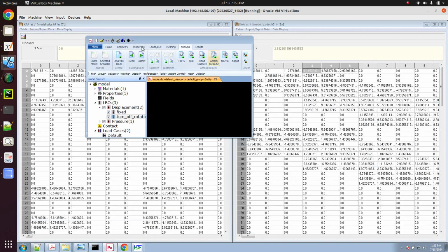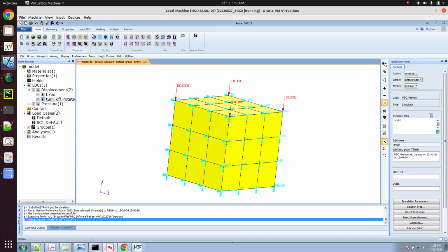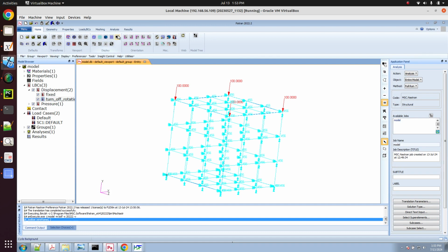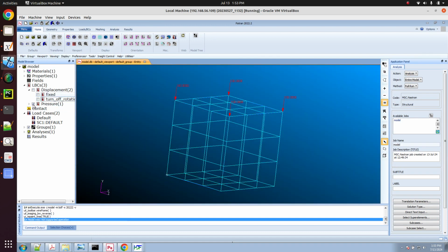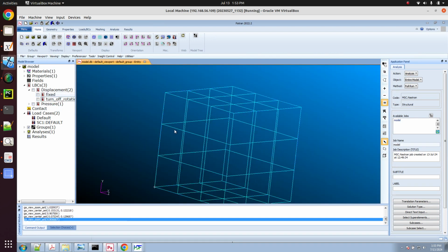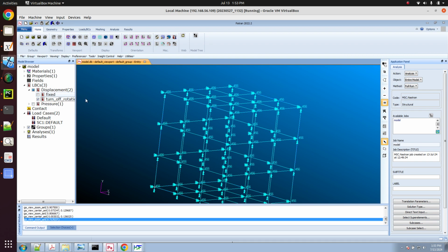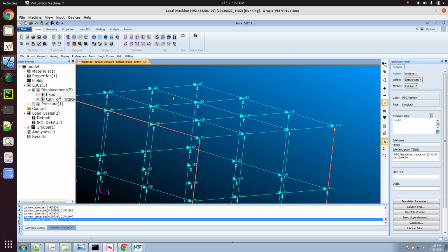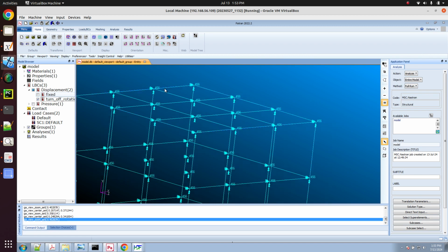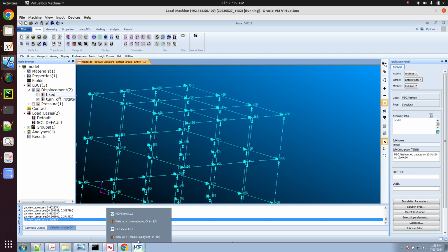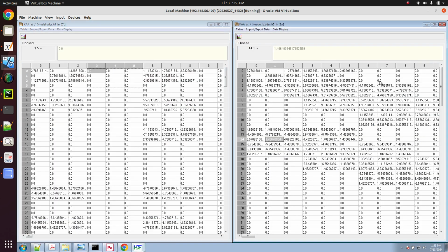So if you recall a few moments ago, what we went ahead and did in Patran was the following. We said, okay, I know that these 3D elements are not supplying any rotational stiffnesses to the nodes. That's okay. I'm going to say that those rotational degrees of freedom are all zeros. This effectively removes those from the stiffness matrix on the right. So now I can go ahead and perform the inverse and find a solution for this scenario.